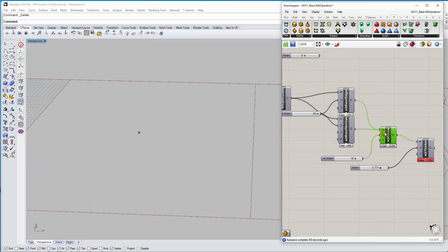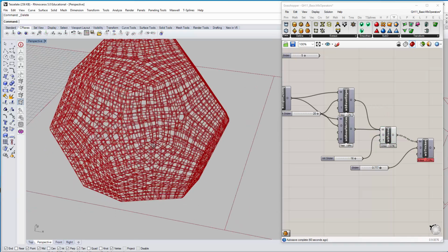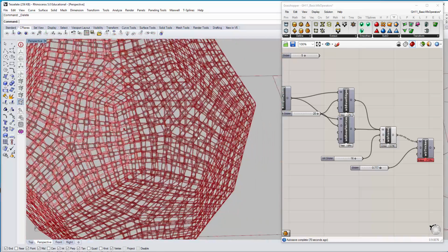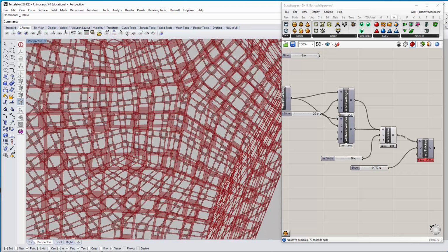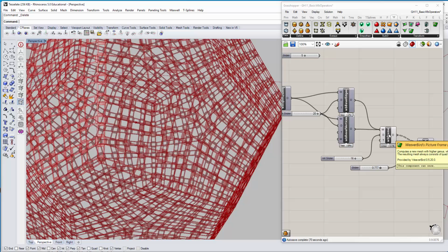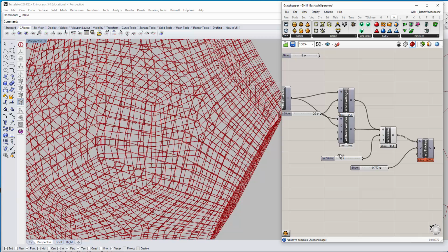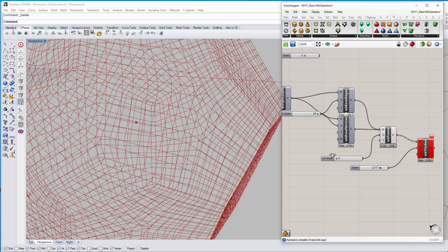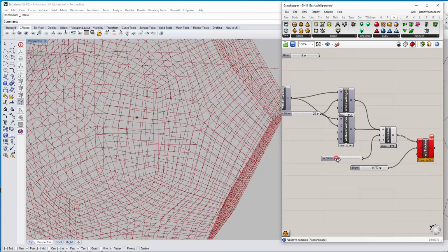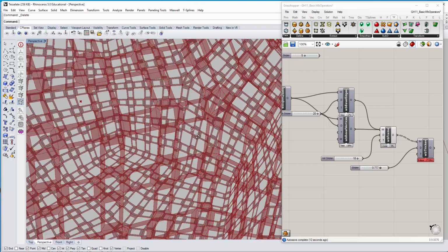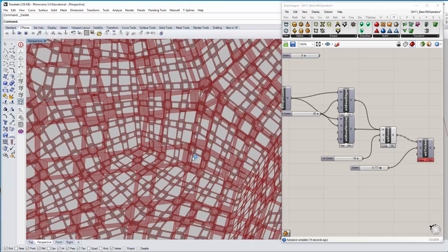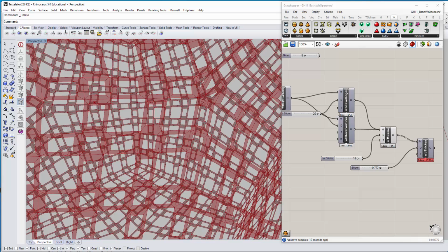Then I drop both of these inputs into a frame. Weaverbird frame takes those and basically does an inwards offset. So it's like a picture frame. That's why the icon looks like that. And the same thing, there's an offset distance. It's this originally as an input, and then as you add the offset, it does that to both this and this, right? So you get a sort of picture framing thing.